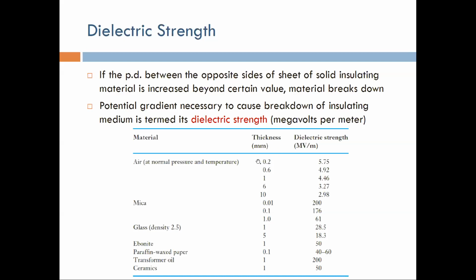Basically, you multiply the thickness by the dielectric strength to know exactly the maximum voltage, or the voltage where the arcing will happen. Okay? Is that clear? Yes. Okay.